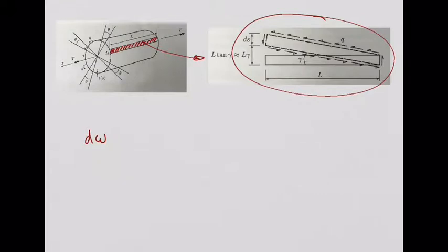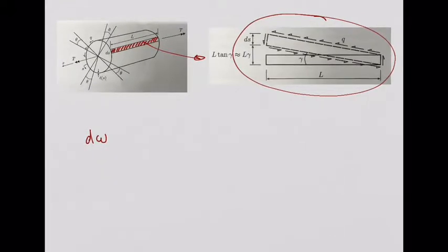In order to do that, this is our initial configuration, this one in red, and this one in green is going to be the final configuration after torsion. So this element will distort, right? Torsion is a kind of distortion, and that distortion is given by this angle gamma that you see there, okay? One thing you need to consider is that gamma is a very small angle. We are in a linear elastic domain where these deformations are very, very small, so it's a very small distortion.